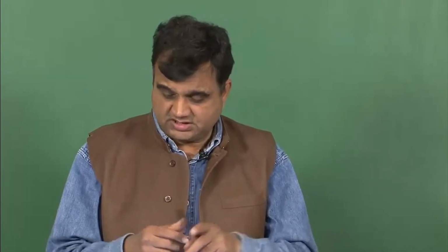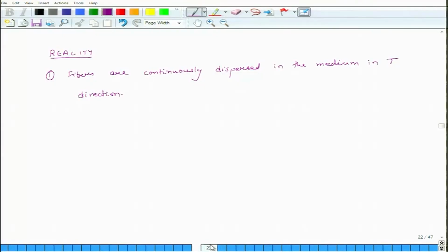See, when you pull something, it becomes longer, but it also becomes slimmer. Okay. So, because of this Poisson's effect, matrix will become slimmer and also fiber will become slimmer, but both these things will not be same because the material properties of matrix and these things are different. So, fibers are continuous. So, what this means is load is shared